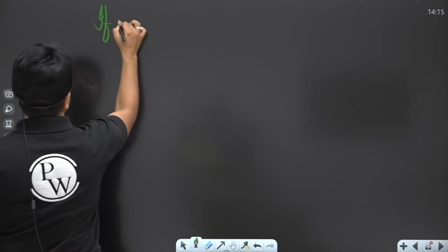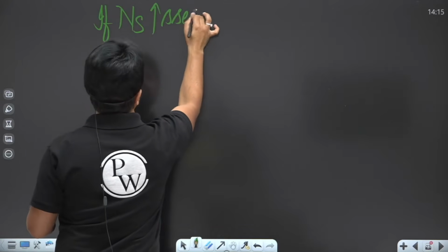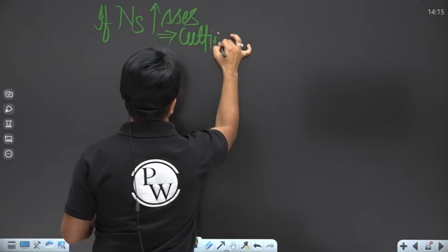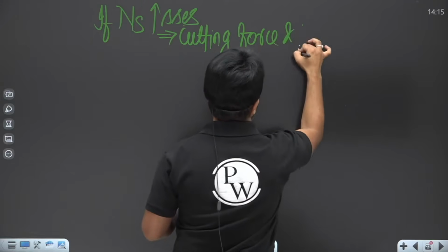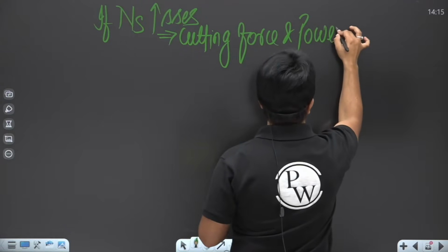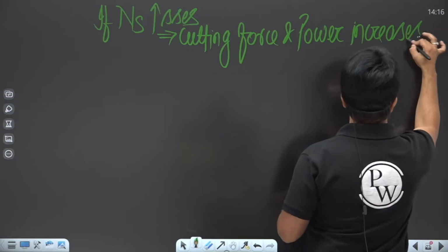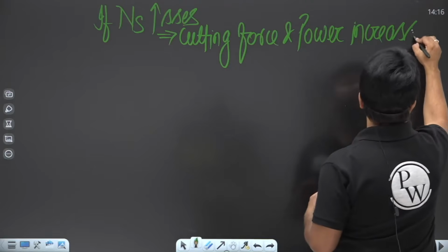If nose radius increases, which implies that cutting force and power increase. Cutting force and cutting power increase.